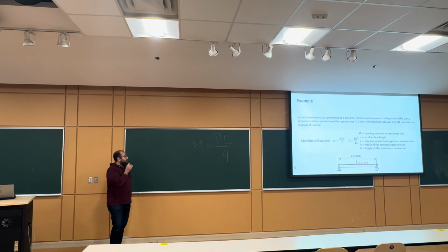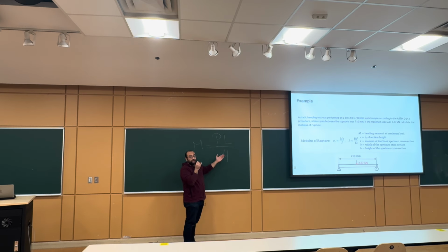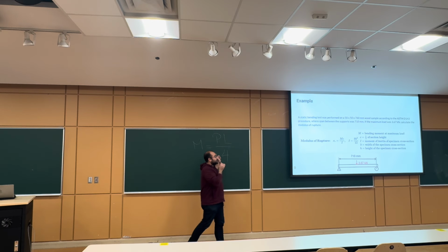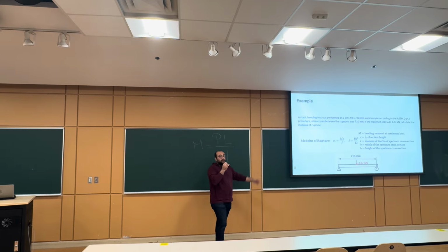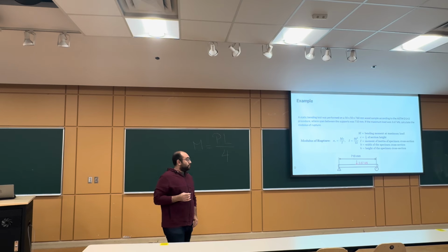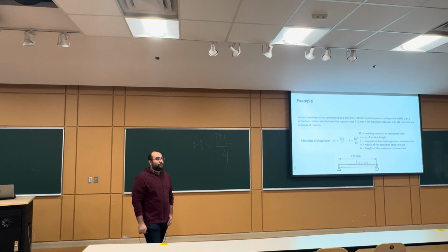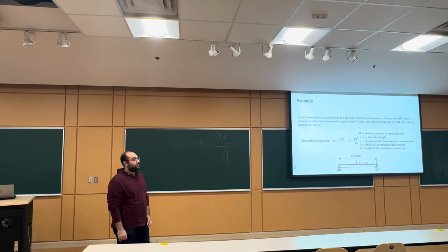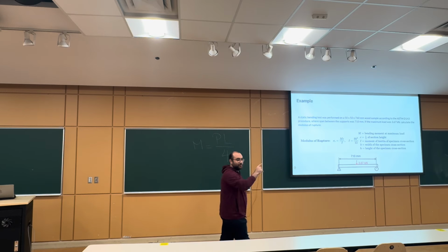So the formula to calculate the moment is actually P multiplied by L divided by 4, okay? So you should calculate the moment using this, plug in the numbers, calculate the moment of inertia, plug in the numbers, and then you can get the flexural stress. Because it's half of the distance multiplied by the distance. That's why it's